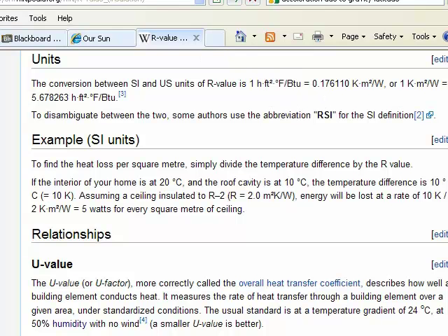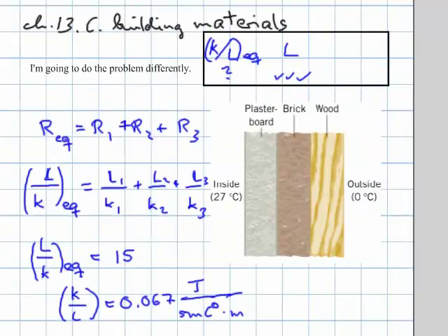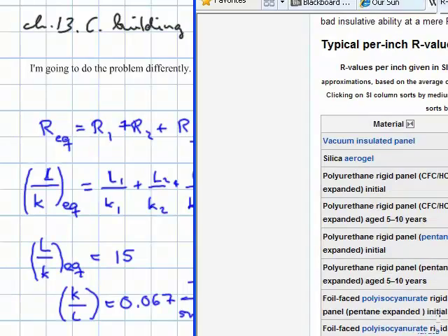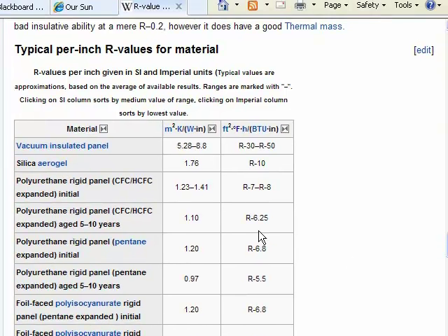Now, as I said, I come up with 85 for the R value, so this one is equivalent to the American 85 R value, but remember I said for the L here I'm using an arbitrary 1 unit, and of course if I call that unit 1 meter, that's ridiculously large. So if I instead just use 10 centimeters, which means each one of them is 4 inches wide, then the value I just calculated, 85, is only 1/10 of that, 8.5. And here's a table where you can see some of these R values, 7, 8, 6, 5, 6, so it's kind of in that neighborhood.